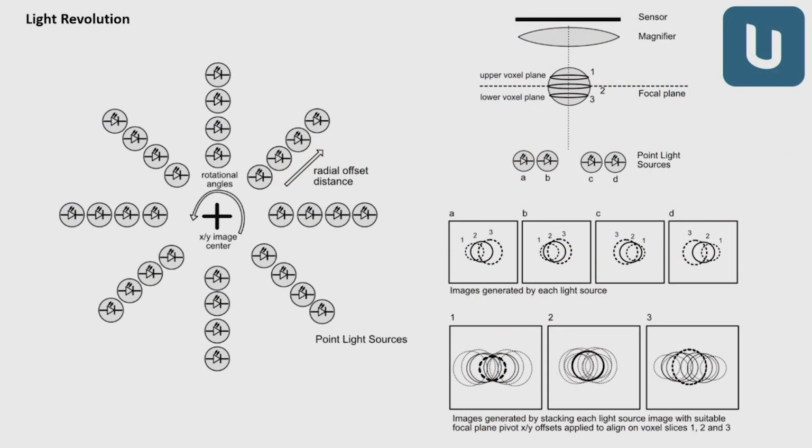So down below it shows how when you imagine those individual sets of images with the different off-axis lights, what it means is the focal plane doesn't move, the center of the slice that you're looking through doesn't move. All the other stuff rotates left or right, depending on the way you're moving the LEDs, or right and left if it's underneath the focal plane. So we basically remove all the stuff that moves and we can pull out the focal plane programmatically.